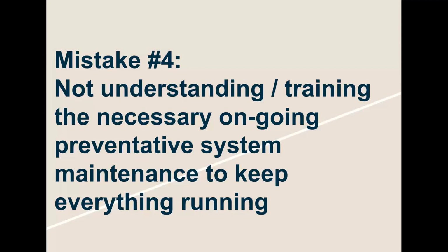And so if you look at our data sheets, we are always publishing what's called a long-term drift spec. And whoever's sensor you might be using, they should have that same standard or same spec. And based upon that long-term drift, you can say, well, in 3 months or in 4 months or in 5 months, I'm going to be 5 to 10 ppm off of my measurement.